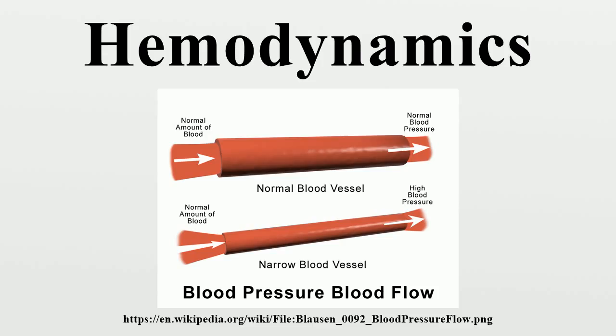For the thin-walled assumption to be valid, the vessel must have a wall thickness of no more than about 1/10 of its radius. The cylinder stress, in turn, is the average force exerted circumferentially in the cylinder wall, and can be described as σ = F/(TL), where F is the force exerted circumferentially on an area of the cylinder wall that has the following two lengths as sides: T is the radial thickness of the cylinder, and L is the axial length of the cylinder.